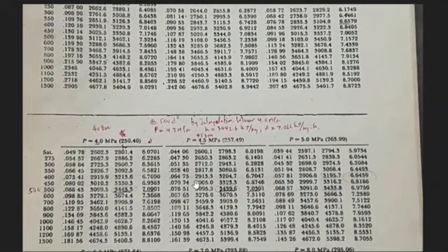But nowadays there is an application. There's an Excel sheet that puts all these values in, and you just use lookup. You just put in the temperature, you just put in the pressure, and it will give you the amount of the enthalpy or entropy that you want. So at 500 degrees Celsius, right? And at 4.2 megapascal or 42 bar, right?